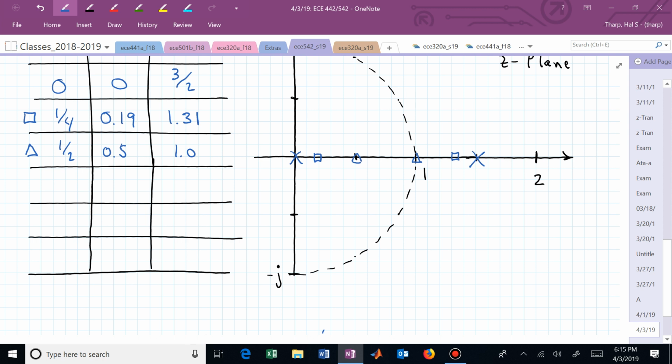So as we cranked up the gain to 1/2, now we're just on the verge of stability, right? We've just touched the unit circle, so that knob that we're adjusting stability of our closed loop system with, we have to get it at least to 1/2 in order for our system to be closed loop stable. I know that this guy is going that way and this guy is going that way.